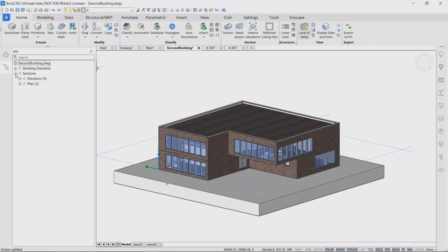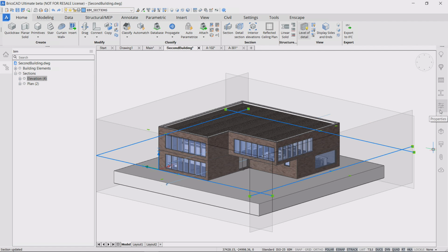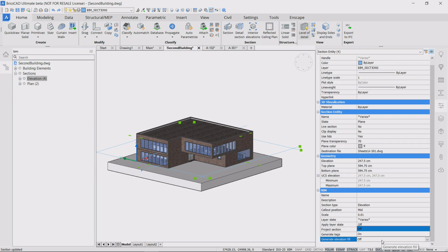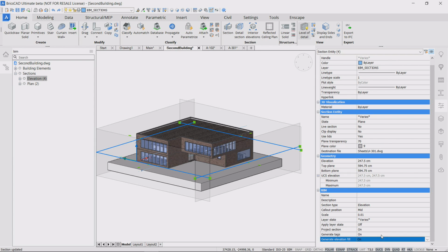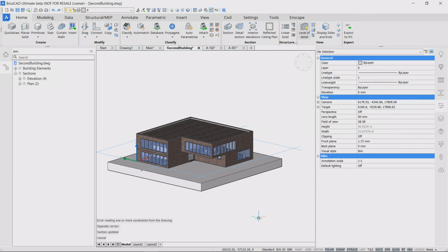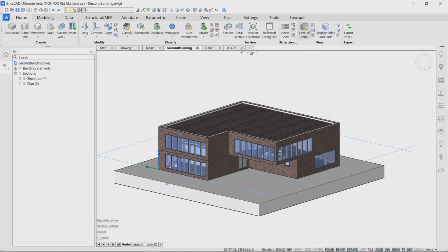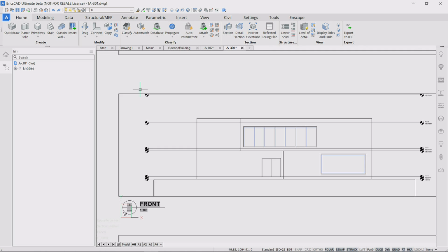It's a property in the section plane, and if we turn that on, you will be able to see the elevation after all. This elevation is specified in the composition of a wall. So if we change the composition, we will also see the hatch pattern appear. That's what we're going to do next.